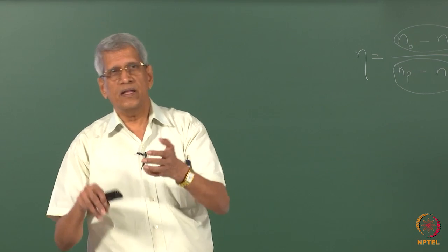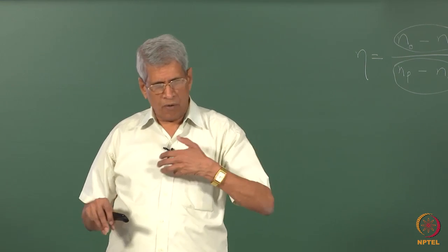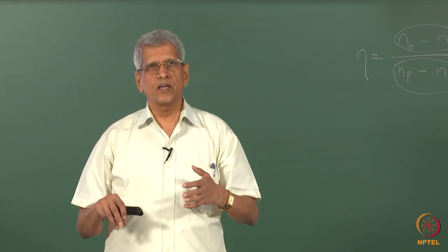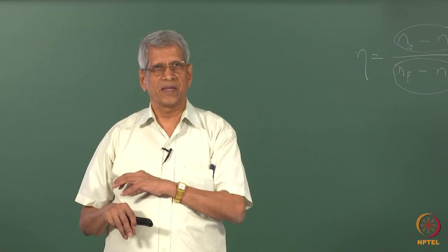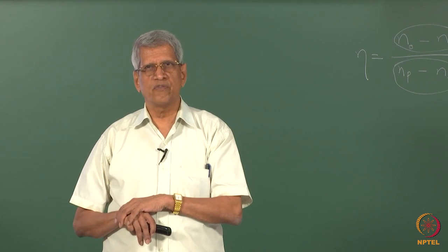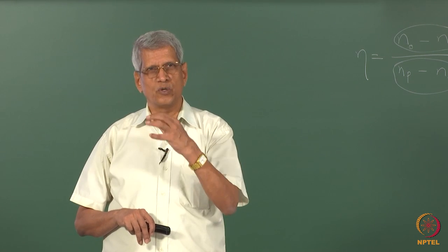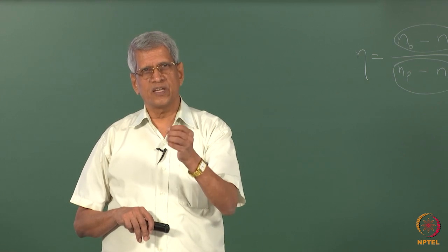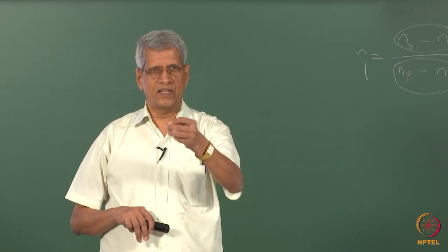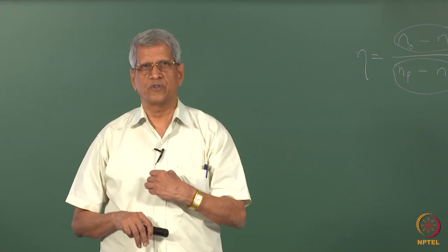But in what I described just now, we are not talking about how we are removing the atom. Logically, the easiest way in which a vacancy could be produced is first creating a vacancy on the surface and that vacancy moving inward by diffusion.